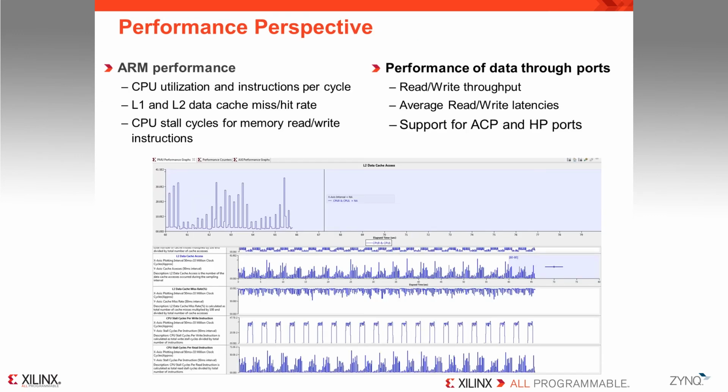After you have your code working, it is important to understand its runtime characteristics such as speed, memory, and resource usage. The Xilinx SDK provides an extensive collection of graphical performance modeling and profiling tools that allow live, continuous display of results from within the processor system or at the interface between the processor and the programmable logic. You can use this information to find the critical pieces of code and optimize their performance in the design.